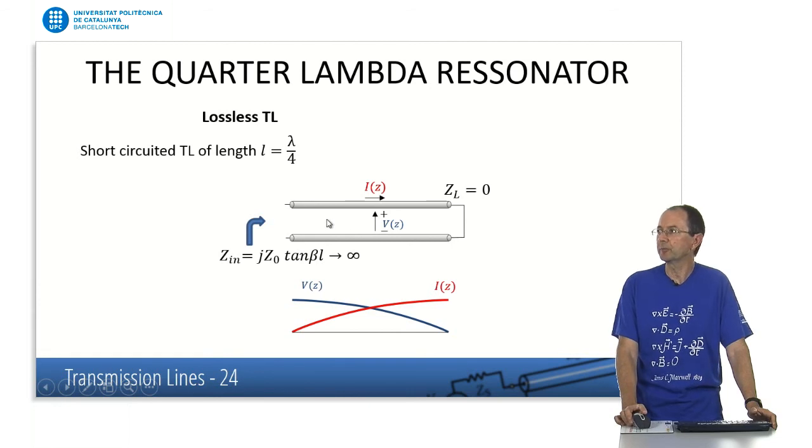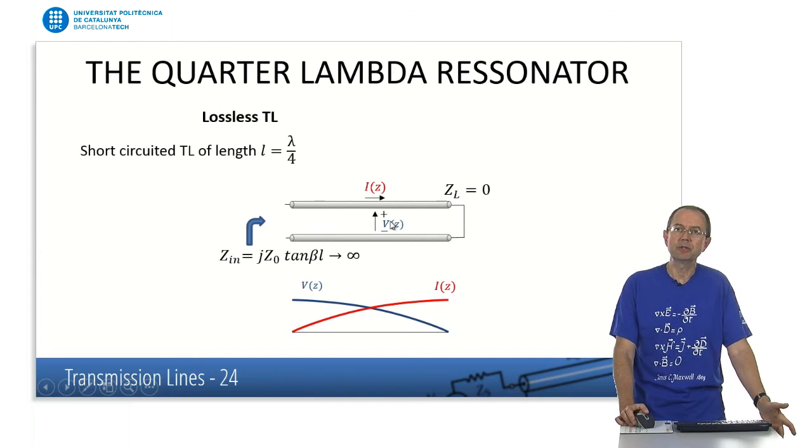So a wave that progresses here to the right is going to have a total reflection coefficient, -1 in this case, and when it goes backward, the reflection goes backward and reaches the input port, we have again a total reflection situation, in this case with a gamma equal to 1. So actually we have here a piece of a standing wave situation, where we have waves going back and forth, and they can be sustained in time.